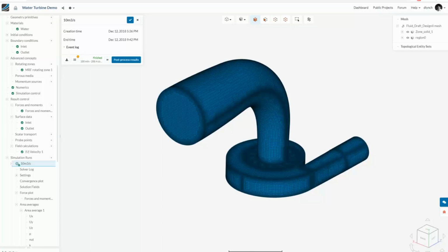The cavitation is more likely to occur where you've got very high flow and very, very low pressure. So if we drop below the vapor pressure and then the water suddenly vaporizes, that's where we're going to start seeing cavitation. In addition, in one of our previous webinars, on pump design, we also visualized a cavitation number there. So you could also check that out to see how we did it.